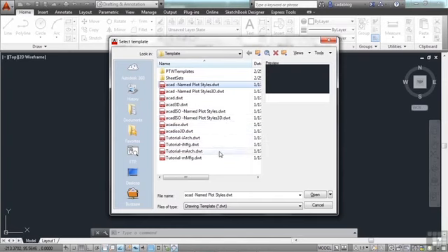These last four details here are used with the tutorials that come with AutoCAD. These are architectural and manufacturing or mechanical drawing types. They also come in imperial units or in metric units. So the imperial are set to like feet or inches, and the metric are typically a millimeter, centimeter, meter type setting. For the majority of the things that we're going to do, we're going to use the AutoCAD.dwt template file. Select it so that it's highlighted, click open.